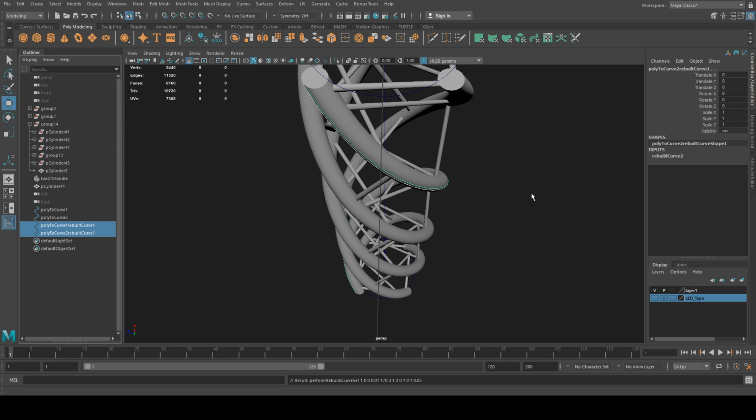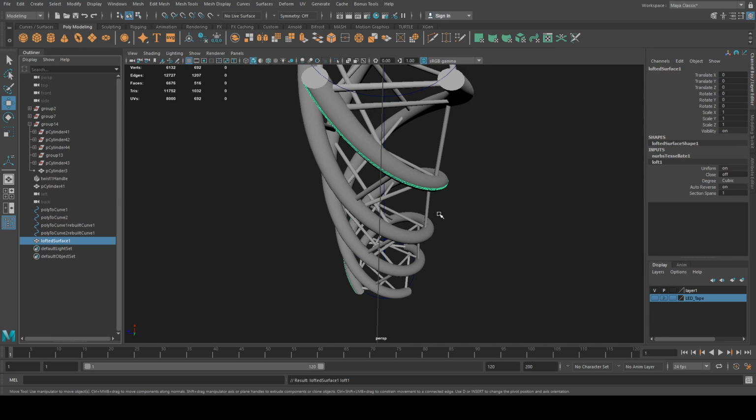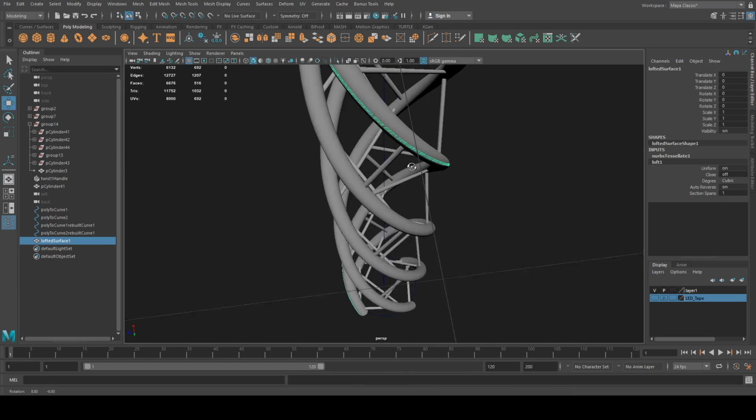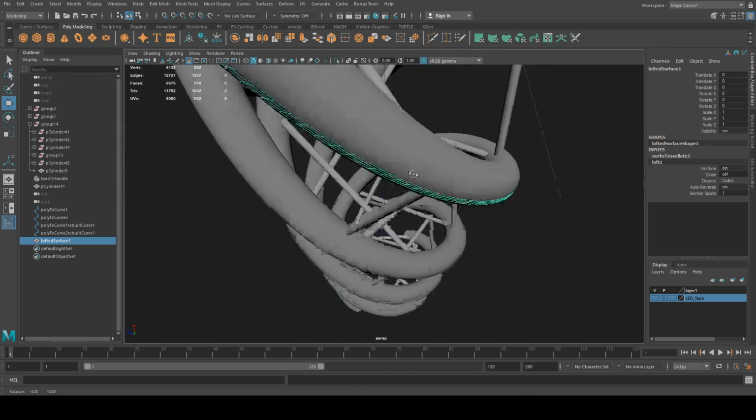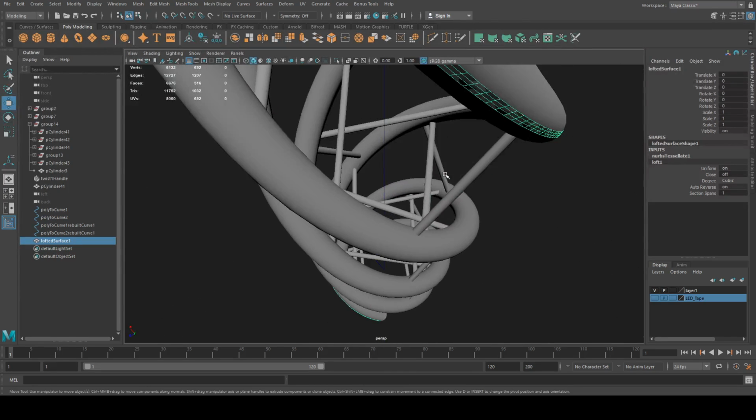And by going to control points, those CVs, those curve points that we set in the section of spans that we set in the last action, those are now going to become individual polygons, 1 polygon per pixel. So I'm going to go ahead and loft that. And if we zoom in now, you can actually see that it's subdivided more than I want.